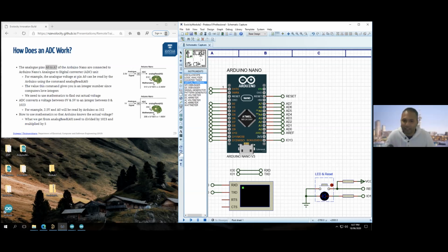You only need to use the analog pins if you want to look at a time varying signal, like a sine wave, and you want to know exactly what the voltages are or represent the sine wave accurately. Okay. The analog allows you to measure anything between 0 and the maximum voltage, anywhere in between, where digital is just 0 or the maximum voltage. Okay, I see.